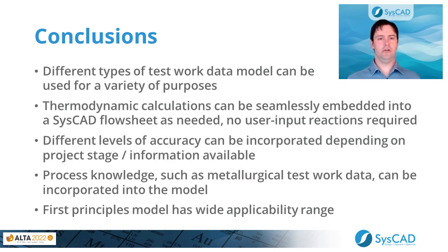A little bit further, we can use different types of test work data. It can be used for a variety of purposes, depending on the stage of project you're at and the information you have. You can use thermodynamic calculations seamlessly embedded in a SysCAD flowsheet, and no user input reactions are required. It's based on free energy minimization. And depending on where you are in the project, you can use different levels of accuracy. You can increase your model accuracy as you go.